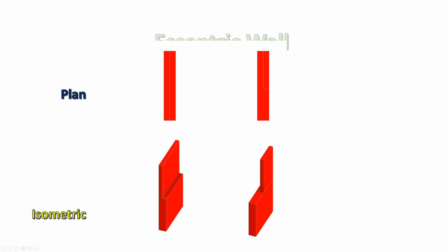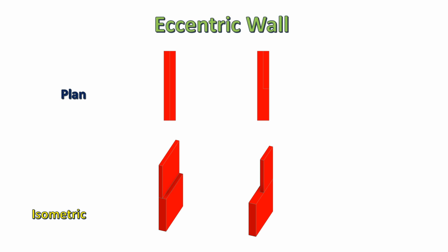In a multi-story building, it is common that there will be an eccentric wall. The eccentric wall could be modeled as actual in the main Revit model. It is the responsibility of the structural engineers to control structural behavior when transitioning the Revit model to the finite element model. Basically, there are two methods to handle the eccentric wall.